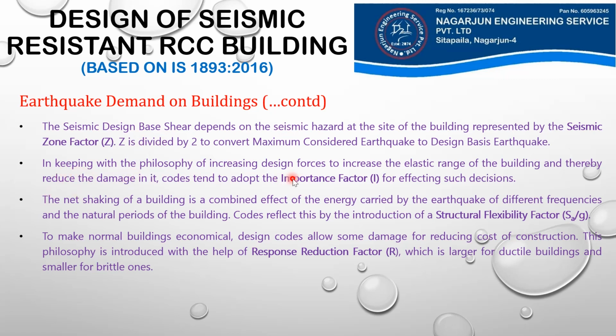In keeping with the philosophy of increasing design forces to increase the elastic range of the building and thereby reduce the damage in it, codes tend to adopt the importance factor for effecting such decisions. So the higher the importance of a building, the higher will be the importance factor, and when we use a higher value of importance factor, we are increasing the design forces to increase the elastic range of the building.